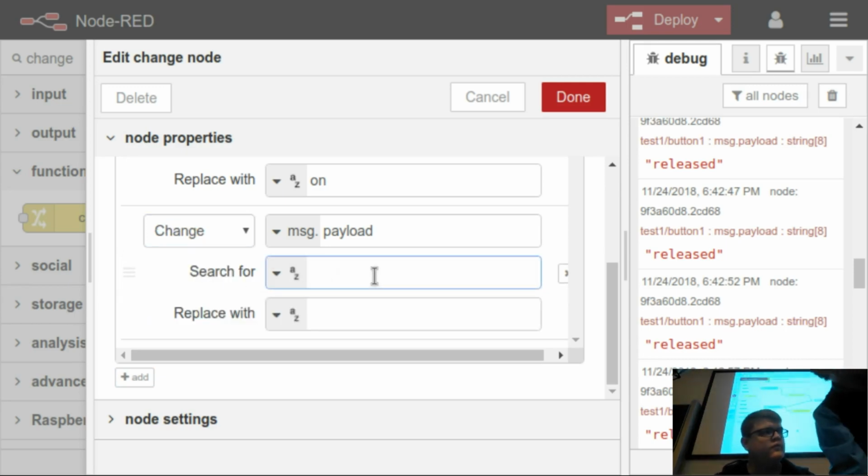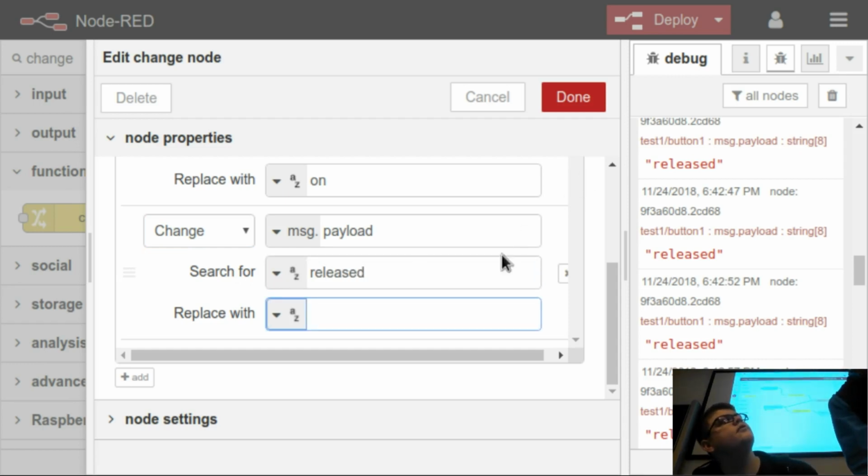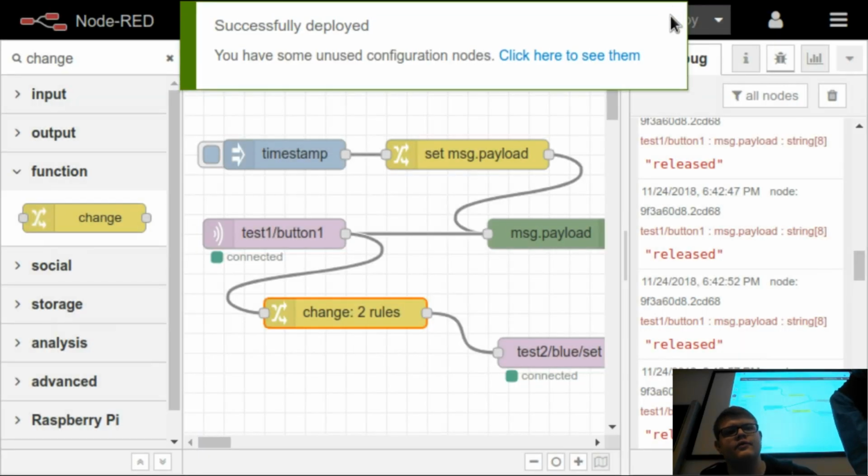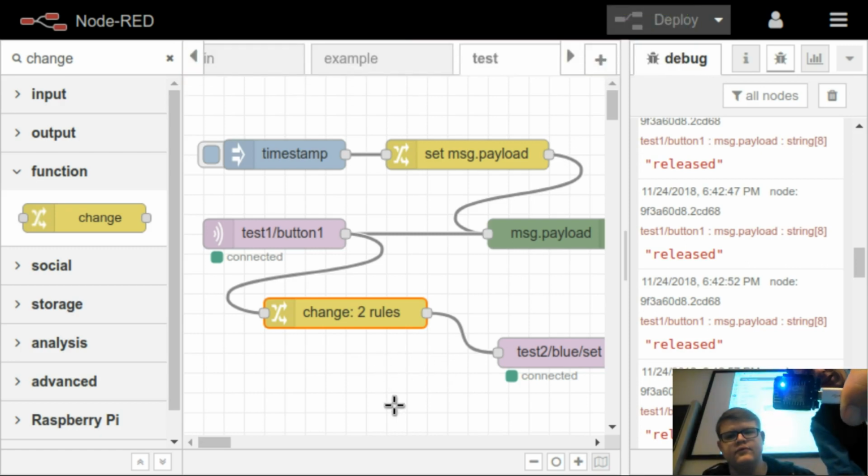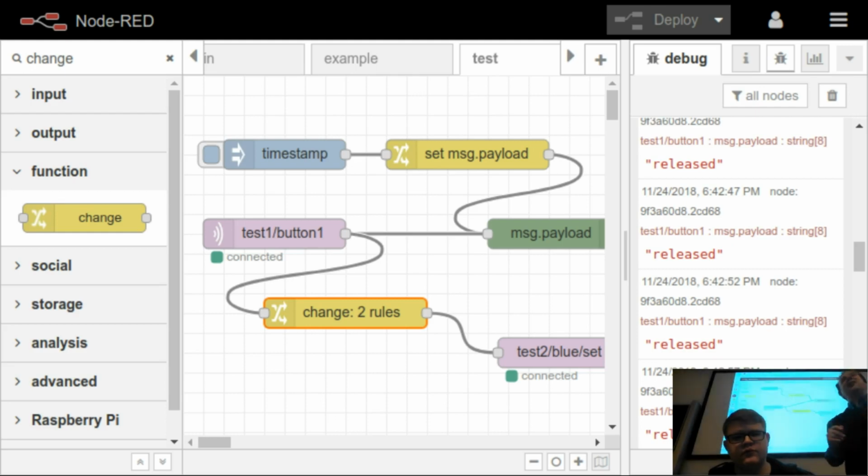And I don't know if you guys see this. Yeah, see the LED. If I press the button, the LED goes on. So we're nearly done with the hello world. We just need your little idea now how we can do the toggle. I'll show this to the camera too. I switch it on when I press it now and release it now. So that's pretty good, but it's not exactly what we want. We want to actually press and then toggle the state of the LED.